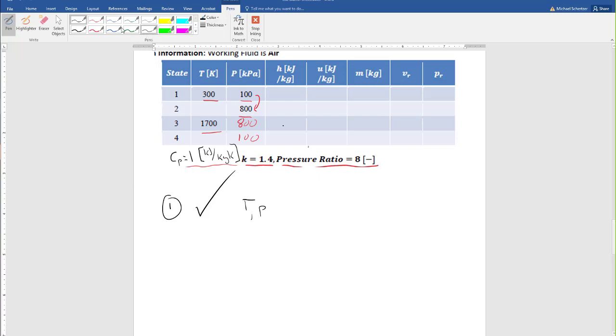So now here, because it's an ideal gas, I need to know which are the isentropic processes, right? So this is an ideal compressor, which means delta S is equal to 0. So as I move from state 1 to state 2, this is an isentropic process. So I could call this, instead of state 2, state 2S. Although in this case, there's no isentropic efficiency, so I don't have to differentiate it that way. But this reminds me that I can use an isentropic relationship.